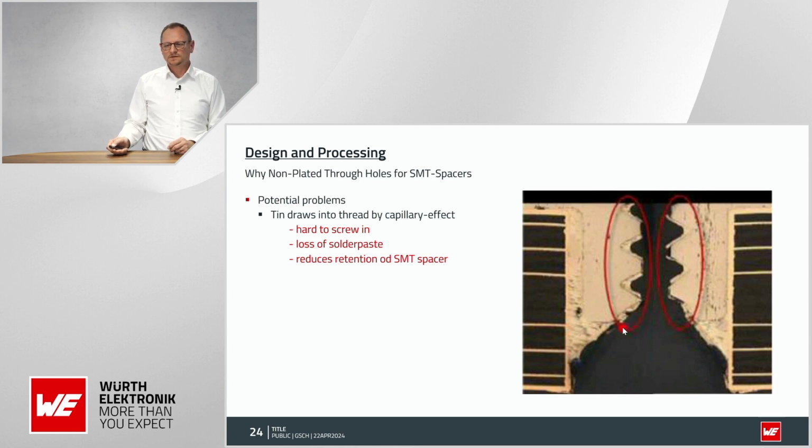And we can clearly see that by capillary effects, the solder went up all the sides through the thread. Now imagine how you want to get a screw into that thread. It will be really hard to screw in, and at the end the solder paste that you find inside of the thread isn't enough anymore to guarantee the full strength. And therefore it reduces the retention of the spacer.